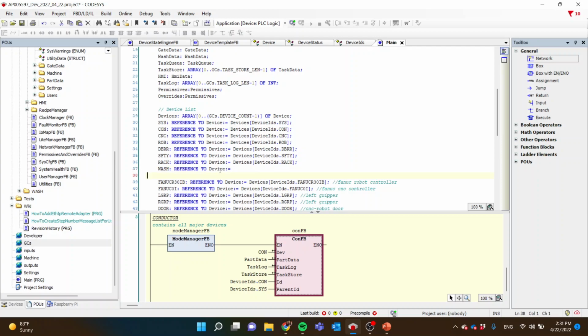So we're using this device data structure, and we need to tell it here, in the assignment, which specific element in that devices array that we want to use. And so an easy way to do this, again, is to reference that enum. And so that's why I want to make sure we're keeping that enum sequential, because it is ultimately corresponding to this device array.